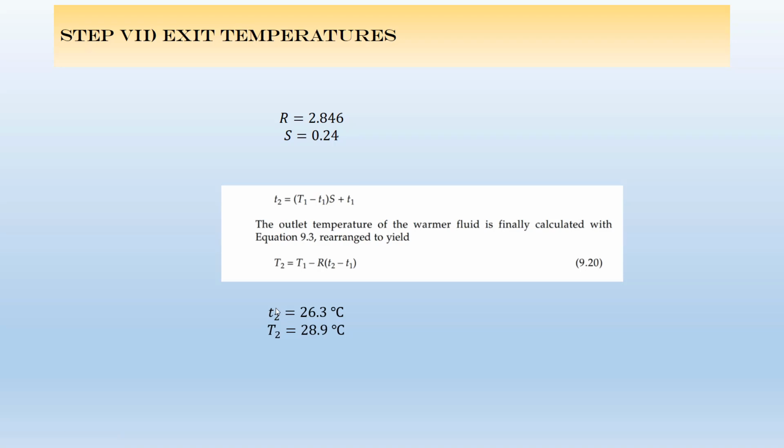between this new average temperature and the initial value that you used to find the thermophysical properties is less than actually 50 degrees centigrade. You are good. You don't need to repeat calculations. So this is the first part.